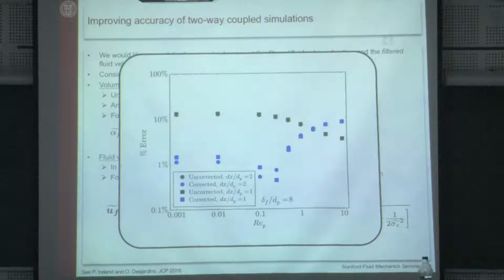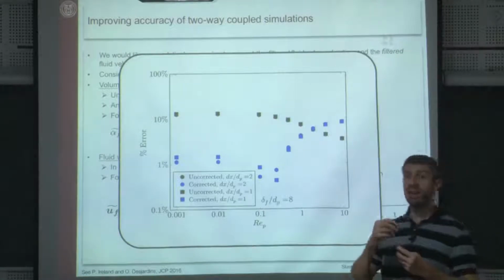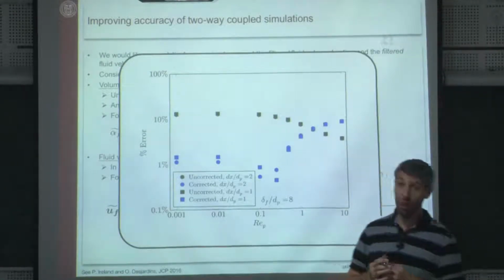What I'm saying clearly is that if you're particle A, then your own wake shouldn't be something you feel, or else it's a bug. You're misusing the classical tools, particularly you're misusing classical drag correlations. But if you're particle B behind particle A, it is a good thing that you would be feeling explicitly from the solution the effect of particle A. Are we doing enough? Are we capturing this effect enough? The answer is no, and we know that.